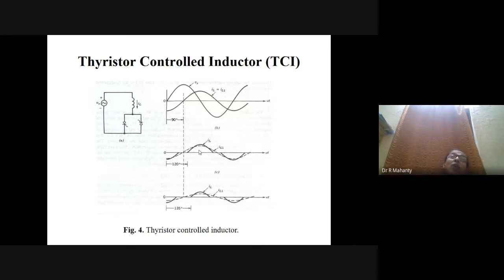Okay, therefore, apart from the harmonics which are present in the system, you have used a thyristor switched capacitor with a controlled inductor, and the scheme is injecting additional harmonics into the system. And why are you using this? For displacement power factor. You want to reduce the angle between the fundamental component of current and the voltage. But in that way, you are increasing the distortion in the system.